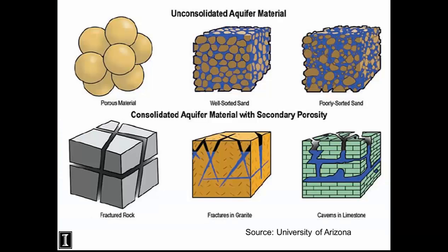And so I mentioned unconsolidated aquifer material. That's sand. It's also silt and clay, which aren't aquifer material, but they're other unconsolidated materials. And there's also rock. So bedrock, sandstone. In some parts of the United States where the glaciers have been, like in Illinois in the northern two-thirds of the state, you have sand and gravel aquifers above the bedrock, and then at some point you reach bedrock and there's either dolomite or sandstone or some other kind of limestone or even granite, other kinds of rock.